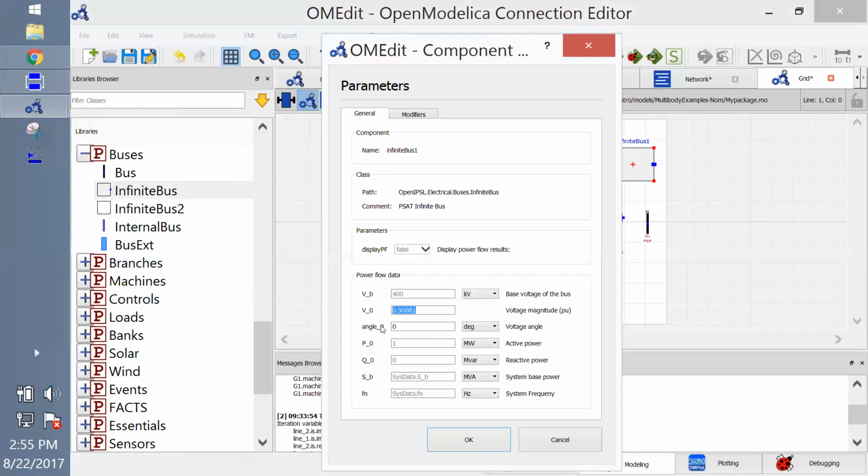Power flow will solve for systems that are dynamically unstable. Power flow gives you no guarantee on stability, absolutely no guarantee. Unless you do that full dynamic model, you have no way of saying if the system is stable or not. You can say some general things, like most likely you're in good shape, but you have no guarantee.